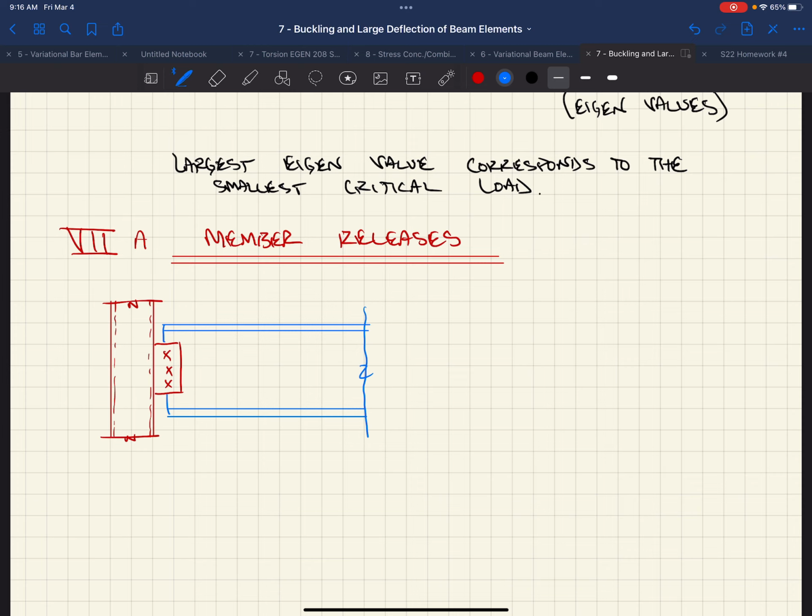So anyway, long story short, as structural engineers, there's a lot of times where we impose requirements on connections based on their design. In this case, if we had long slotted holes and we did just snug tight connections, we might assume that this beam could move in and out as well, right? It's not gonna pull on this column.